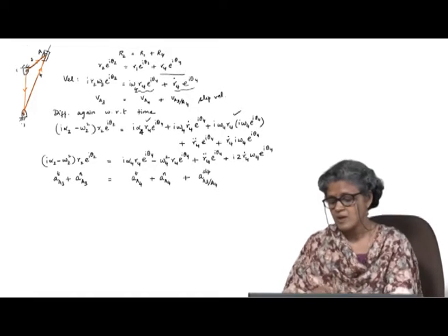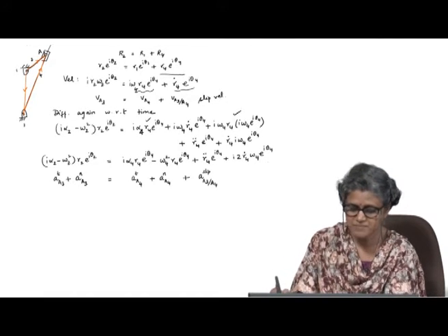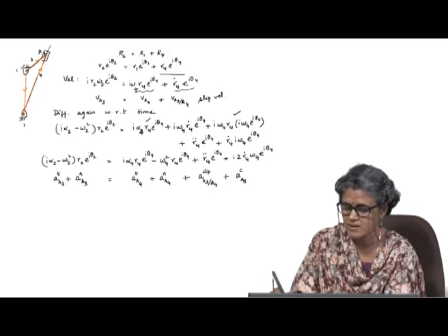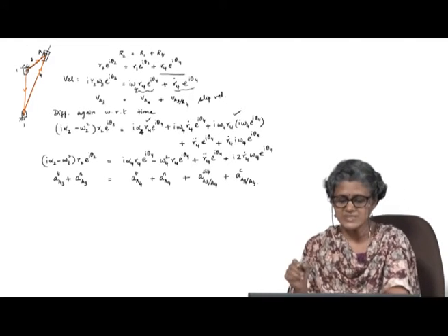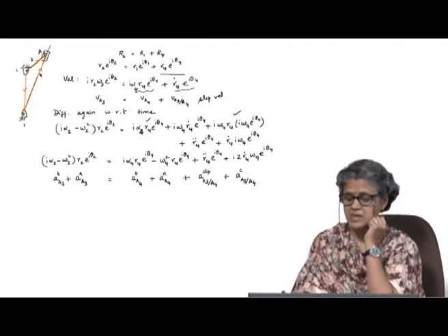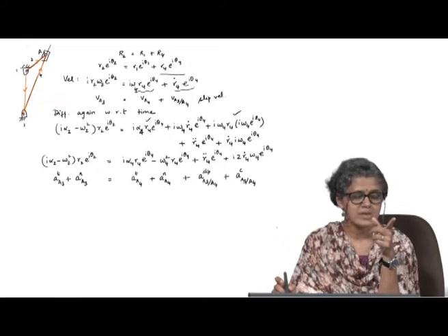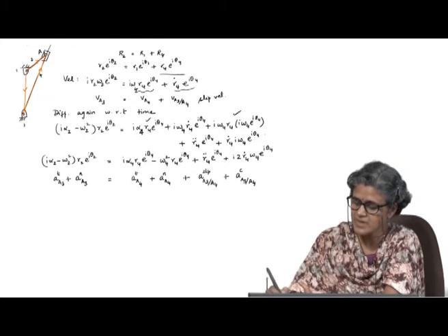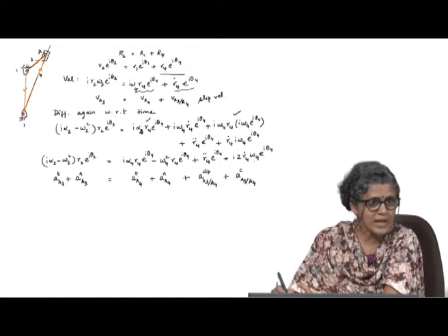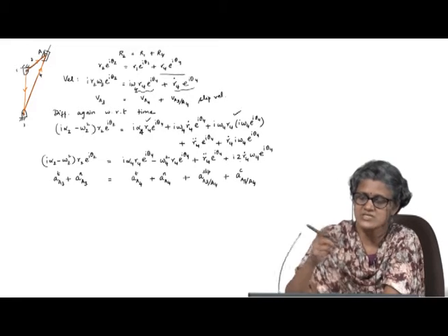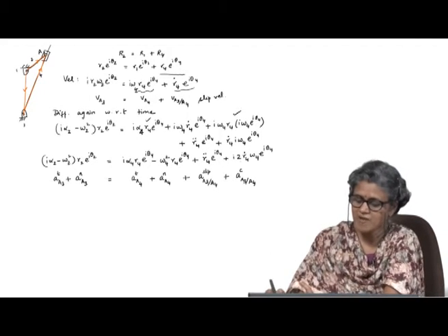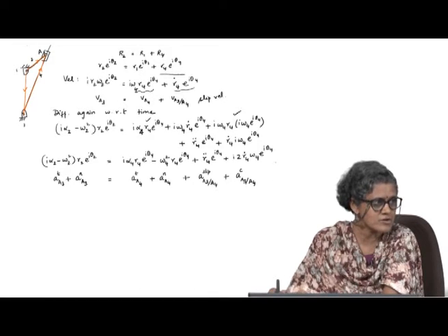That is the slip acceleration, and this term is called the Coriolis acceleration of A. The Coriolis acceleration appears when you have a rotating slider essentially. You have omega 4 and R4 dot, and they are sliding with respect to a rotating path. So, when you have both of those, you will have this Coriolis component of acceleration.